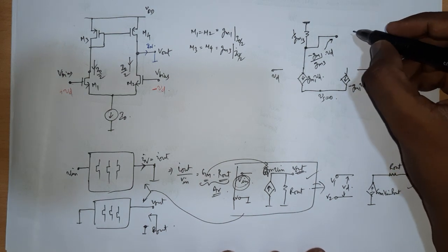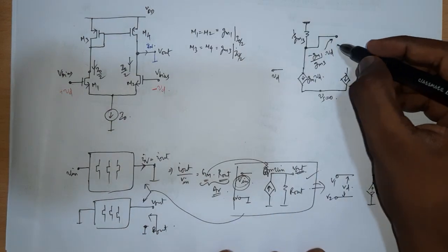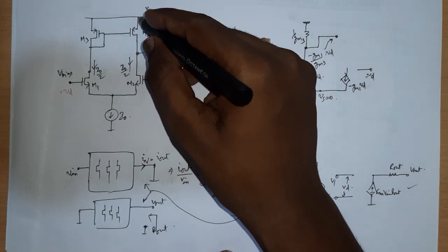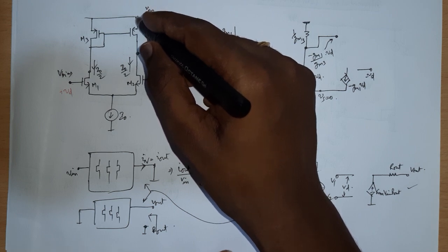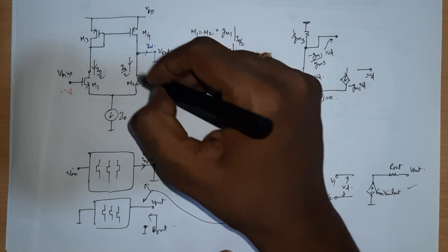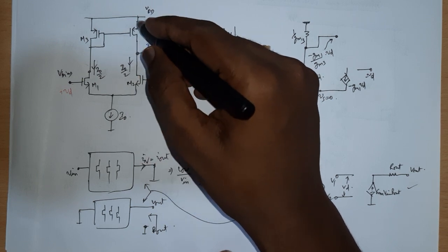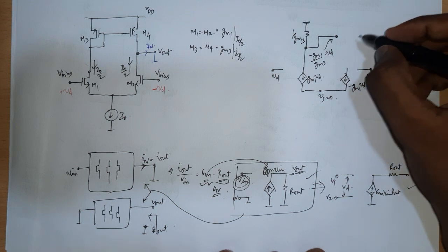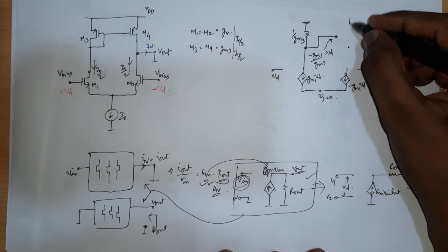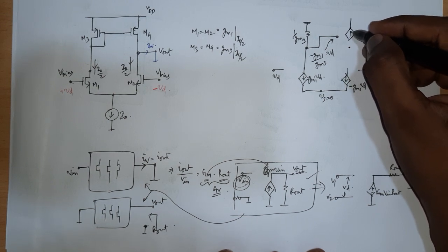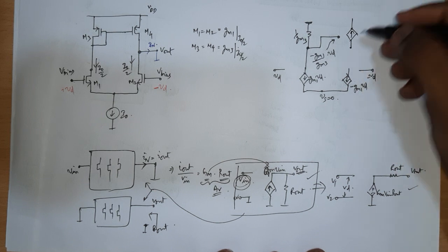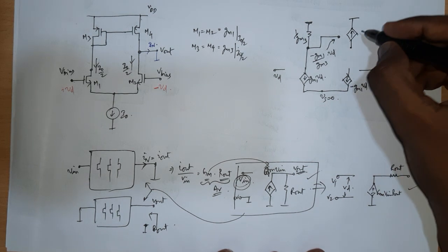Now you have this gate voltage that is established, we have figured out what it is. Now the source terminal is incrementally grounded, right, and this PMOS equivalent is exactly the same as that of NMOS equivalent. So from the drain to source you have another current that is determined by this gate voltage, okay. So you have a current from drain to source like this incrementally, and that is determined by GM VGS, okay,